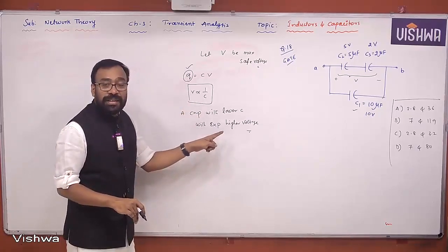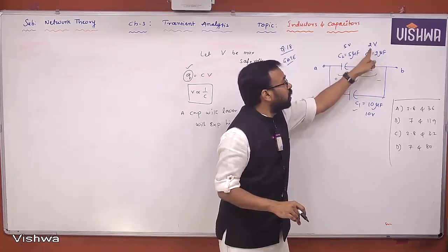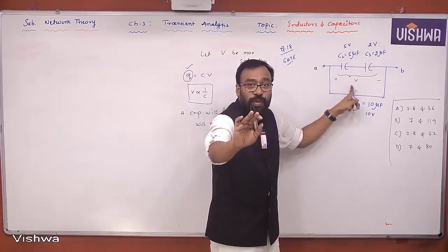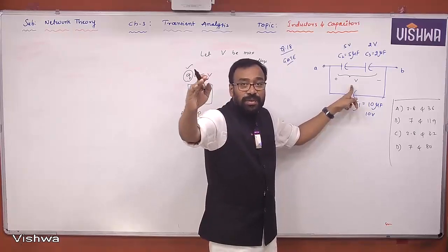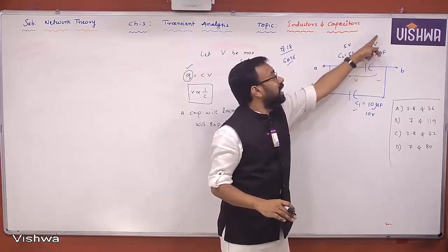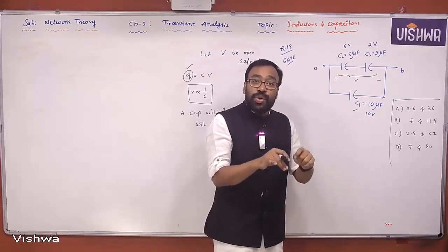Understand all of you? Okay. Now, what is the maximum allowable voltage of this particular capacitor? Because the breakdown strength is already given, 2 volts. Now, you apply any voltage that you want, the highest value, in such a way that the voltage across C3 is not exceeding its breakdown strength, that is 2 volts. That means the V3 value is known now.